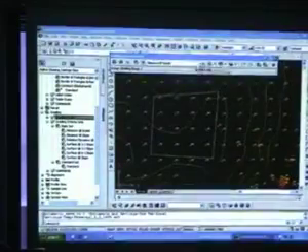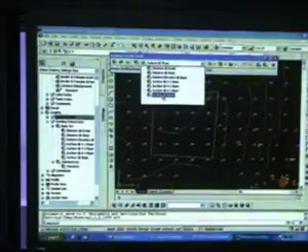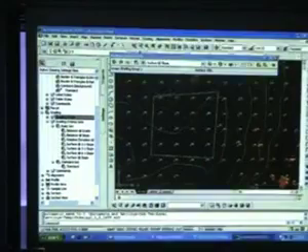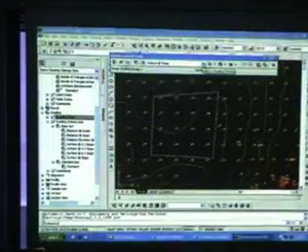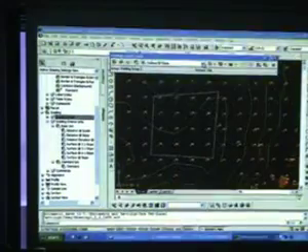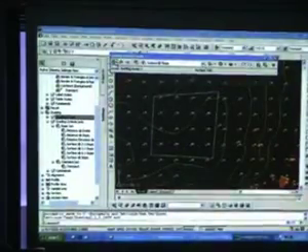So once you switch to basic set, you find this drop down list is exactly the same as what's in the settings. So I'm going to set this at surface at slope. Now we go to the next slide. Slope surface at 2 to 1 slope, right? That means the slope value is the slope gradient. So this is quite good in the sense that it's quite easy.